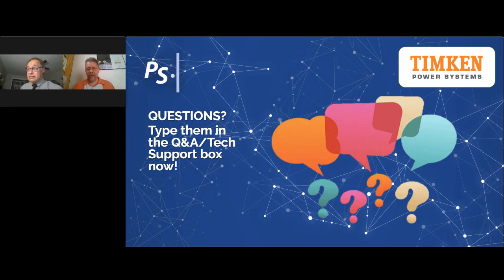Wow, thank you. That's a fantastic question, and that's exactly what I try to do with my analysis. If you look at the paper, and if you go back in the slides, there are specific calculations with which I can estimate the performance: the specific losses, the friction and windage losses, the stray load losses, the iron losses, and the conductor losses. I can use those formulas to a fair degree of accuracy. I can estimate it for any machine size within that envelope, and it's based on the empirical study that I did. So I can use that to estimate it even in an old plant.